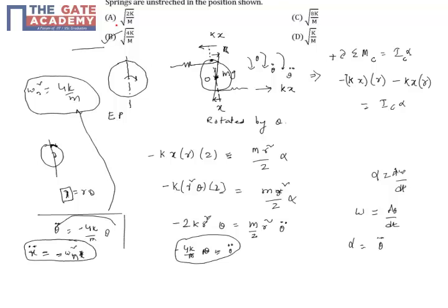So when you have any of these kinds of problems where you are given a situation and you want to find out the natural frequency of vibration, you have to first decide whether it's a linear system or a rotational system. Now we have decided, because the disk is something which can only rotate, you have to displace it by theta, apply the rotational equation of motion, and try to express the degree of freedom, here theta.